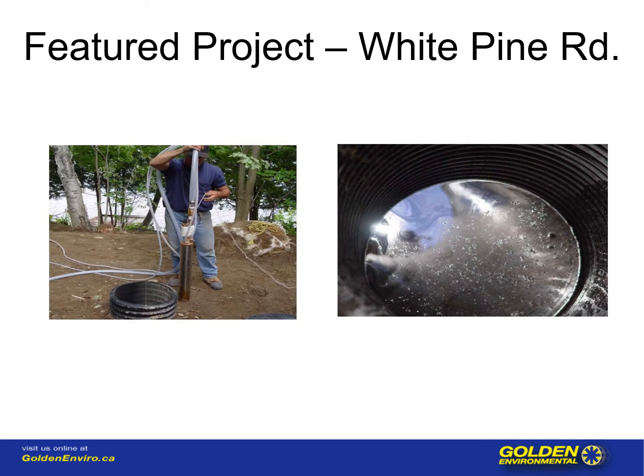This is a photo of our recovery well. As you can see in the photo on the right, there is a sheen of oil sitting on the groundwater. The photo on the left shows how close we actually are to the lakefront. There's the well pump being installed, and this will trap the oil from migrating further towards the lake. Any oil that has moved towards the lake will be pulled back into this funnel as we depress the water table.